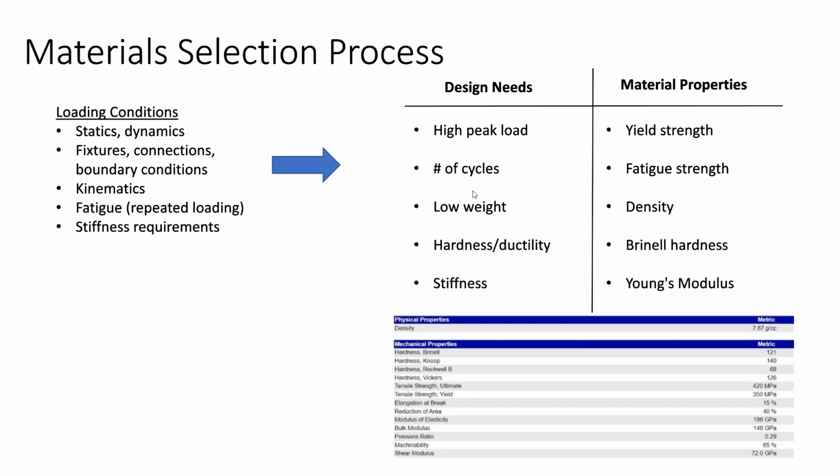What would you say is a secondary requirement? Yes, you're right. It does undergo a lot of cycles, but in this case, the loads on the wing are typically so small that they're not enough to fatigue the part. It's a bit tricky, but I would argue stiffness is the second one because the geometry of the wing is so critical to how it operates that if it's flexible, it's not going to behave the way that you want it to, and you get effects such as buffeting, etc.